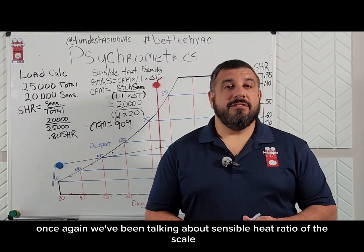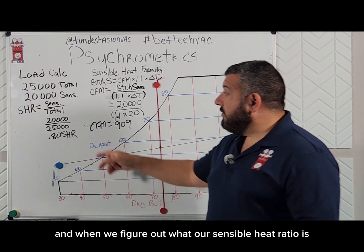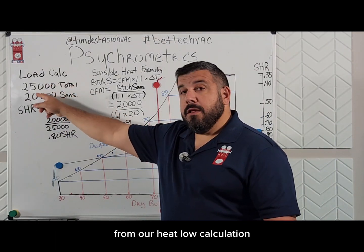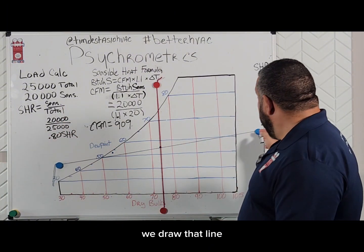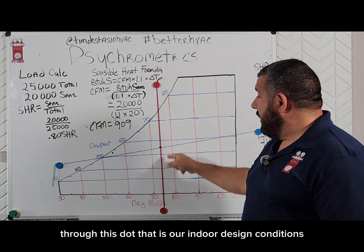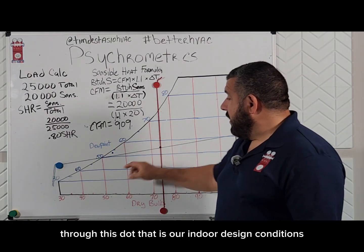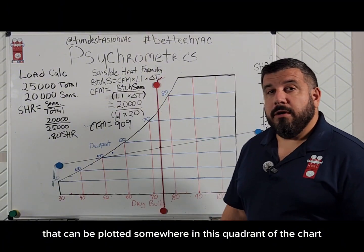We've been talking about sensible heat ratio, the scale that's on the right side of the chart. And when we figure out what our sensible heat ratio is from our heat load calculation, in this case 0.80, we draw that line that connects 0.80 on our sensible heat ratio scale through this dot. That is our indoor design conditions. We need a supply air temperature that can be plotted somewhere in this quadrant of the chart.